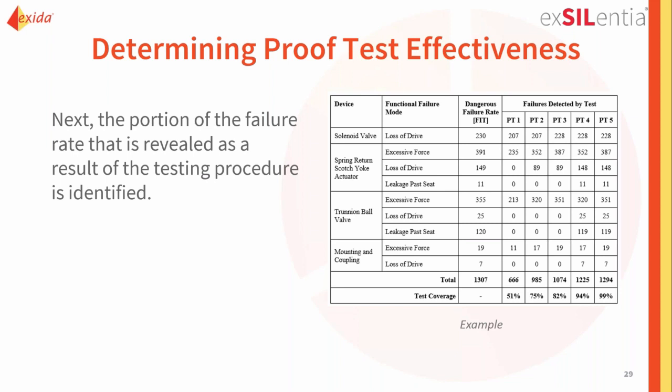It's the partial stroke test. PT2 is the full stroke test. PT3 is the full stroke test at operating conditions. PT4 is the full stroke and leak test. And PT5 is the full stroke leak test at operating condition.